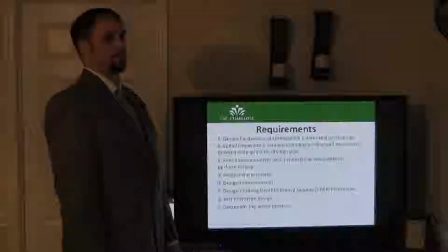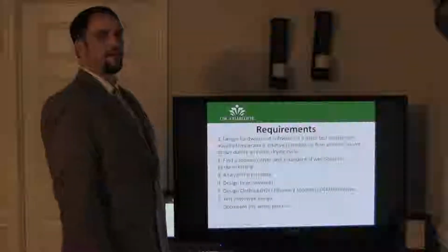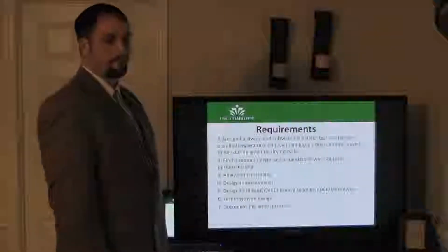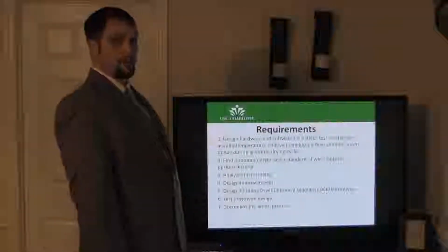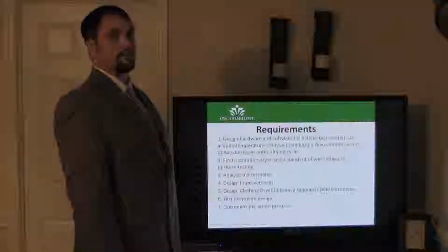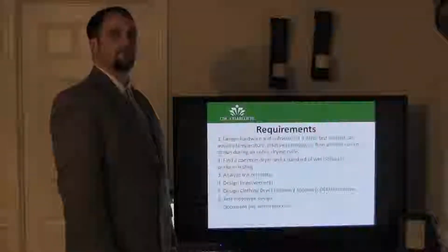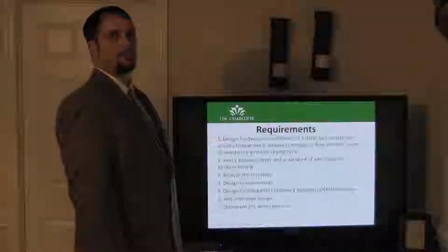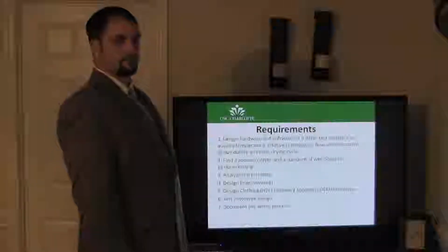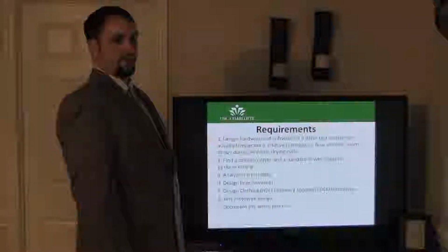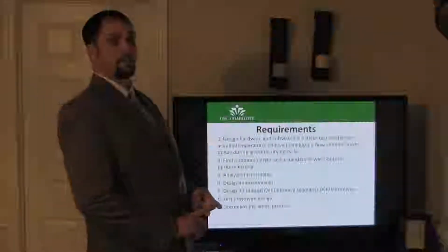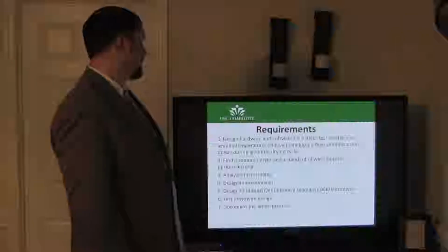Requirements. The first requirement is to design a test set, and this test set is driven by LabVIEW and run on a personal computer. That personal computer uses a data acquisition card to collect voltages from 4 different sensors: one being a current transformer, another an airflow sensor, and then 2 sensors combined, which is relative humidity and temperature, all in one sensor.